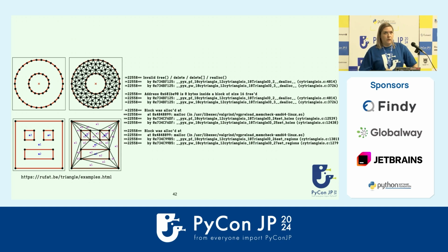Basically, you can add segments or boundaries to your mesh, and then to indicate that it's a hole, you put a point within a closed boundary. So that's what the hole is, and then the set regions is like, if I want to have more control over what the mesh looks like, you can tag, again, a point to say, mesh this region in a different way.